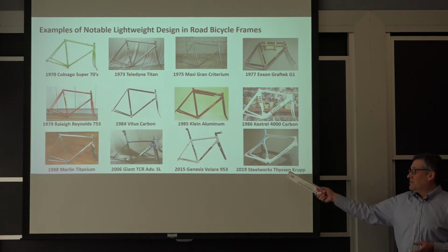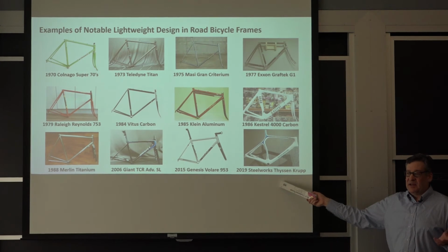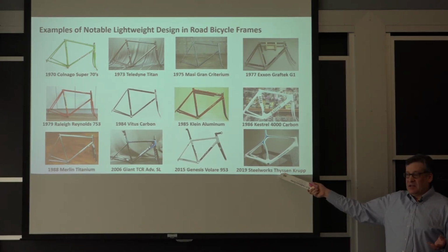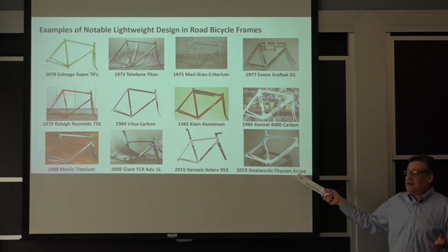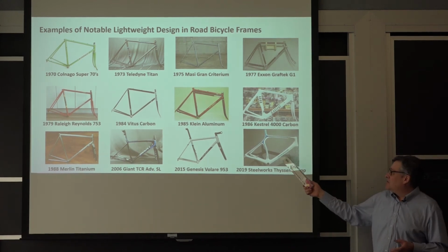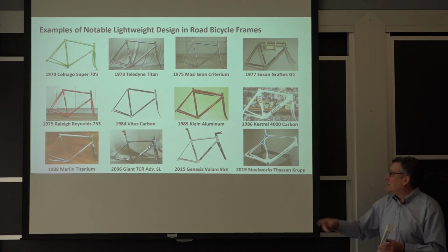So this frame came out like a year and a half or 2 years after I made that pitch. The pitch, I couldn't get any money for it, so it never flew. But it was interesting to me that this frame came out about a year and a half later out of this huge German steel company, which had no business making bicycles. This frame is a dual phase steel, and what they do with this is they stamp the two halves of this together, and then they laser weld it in the center.